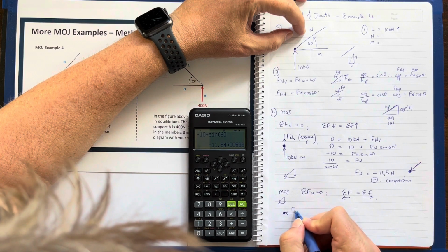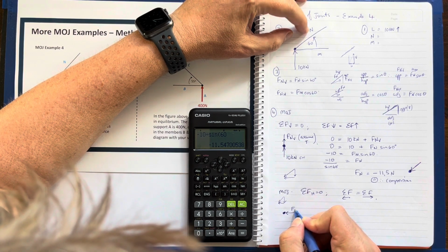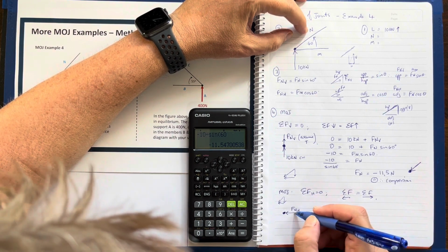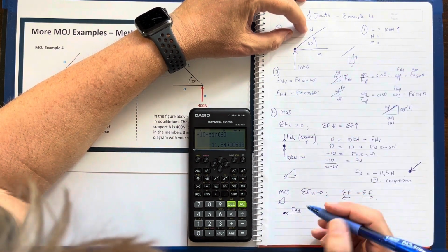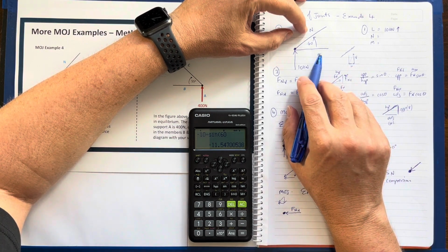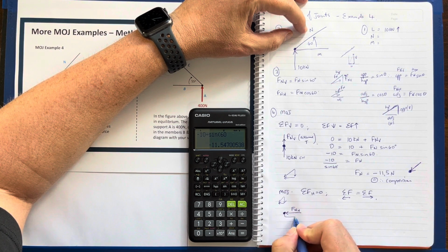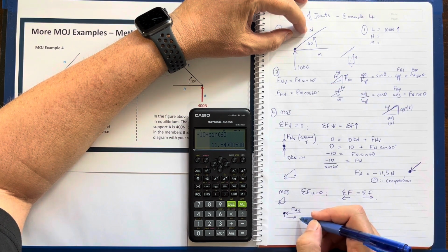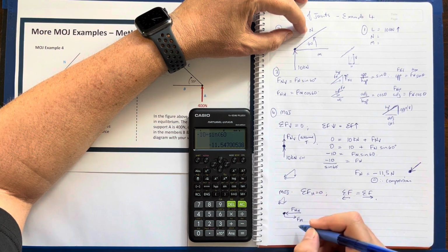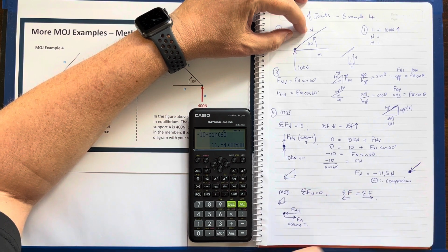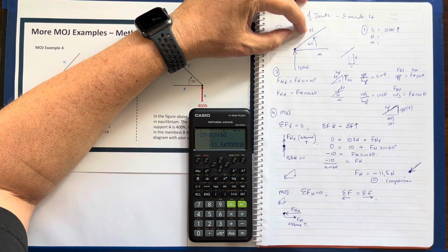So my force of N horizontal is going in that direction. We know what that is as well there, but we don't know what M is, and we're trying to find M now. So we assume that M is actually in tension. The force in M, assume it's in tension, therefore its internal force is moving away from the joint.